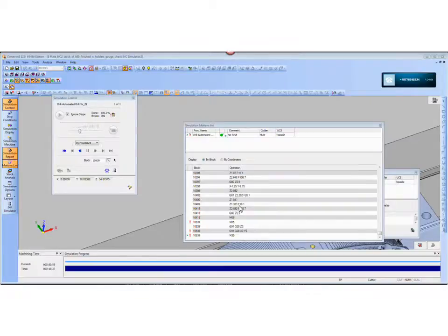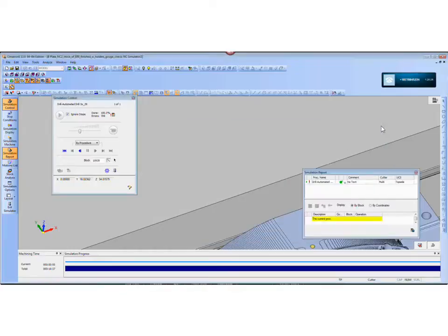And on the retract, you can see that the feed rate is 500% because I want to exit the hole at 500% of my feed rate. I don't see the spindle changing here, but that's just a matter of the post having it pass to the post processor, but trust me, it works. Okay, that's about all I really have to show on the software. Let me go back to the slide presentation here.